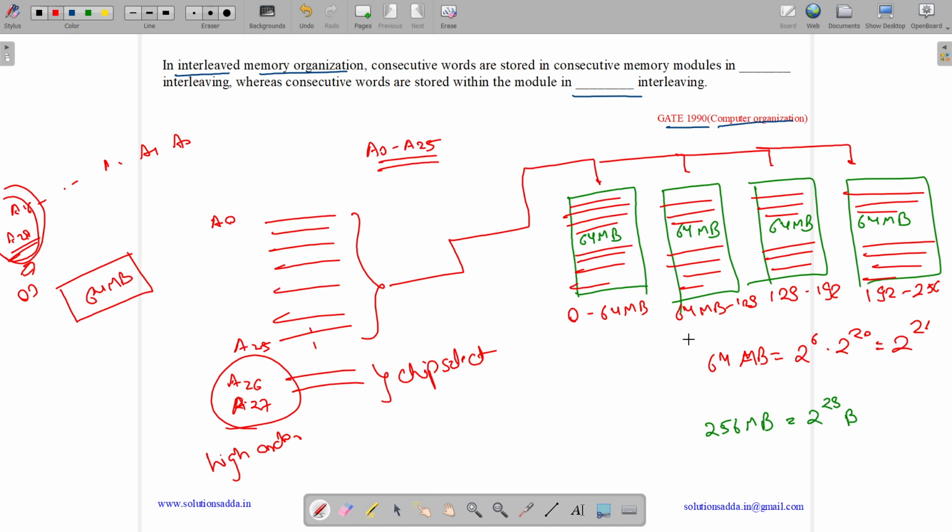Now we will have another solution. So the disadvantage of this is, if we are using consecutive memory addresses like 0, 1, 2, 3, due to this delay, we need to have a delay between read and write. And here also, as we are selecting from the same memory module, delay would be there, so it is less preferred.